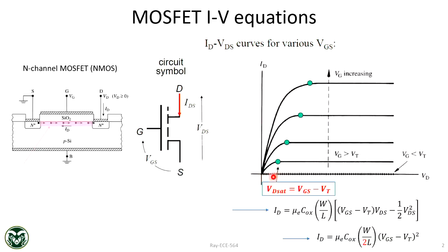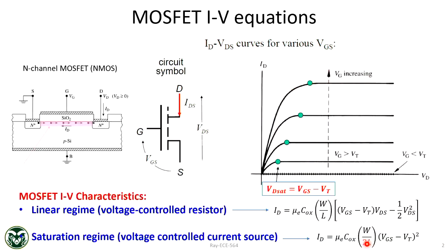One is this low drain voltage, which will give triode or linear. And then there is a saturation region where current becomes independent of voltage. Unlike Ohm's law. Ohm's law doesn't say that, but that's what we assumed, and we'll be assuming pretty straight, without any channel length modulation, pretty much like a square law standard equation in today's derivation or throughout the course, just to make your calculations simple. What I mean is there can be some slope here, but we'll ignore that slope. Okay, and these are the two regions.